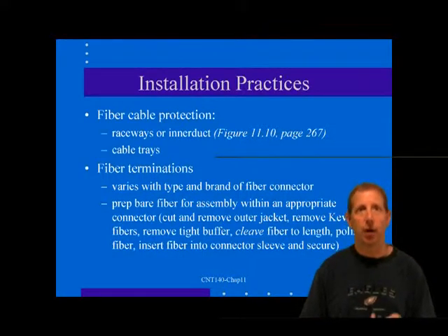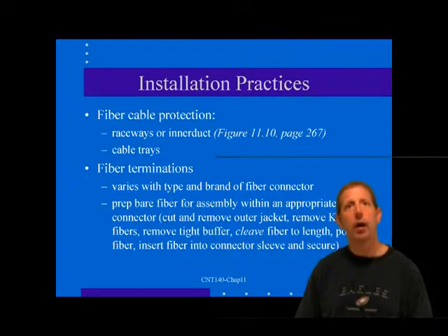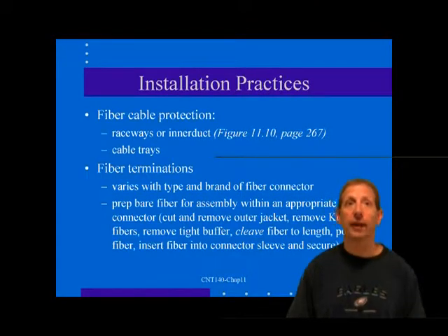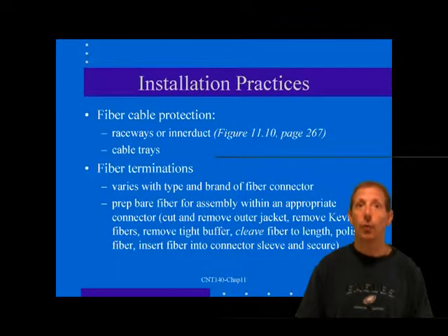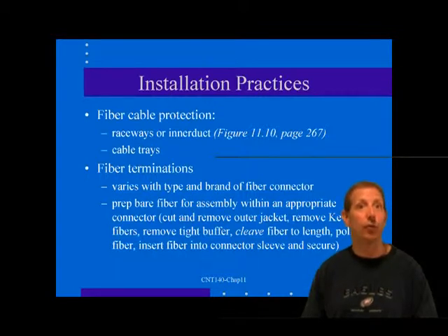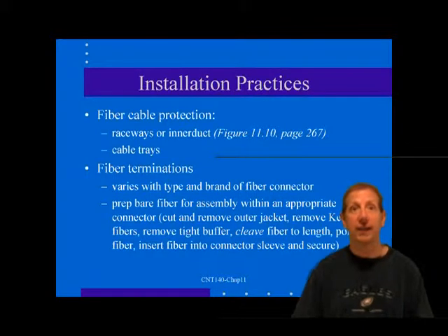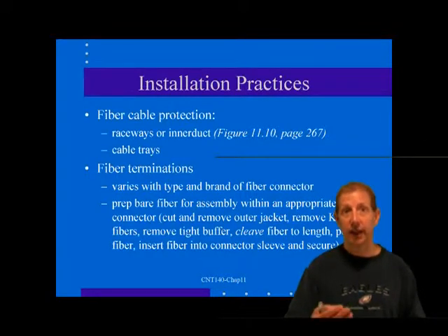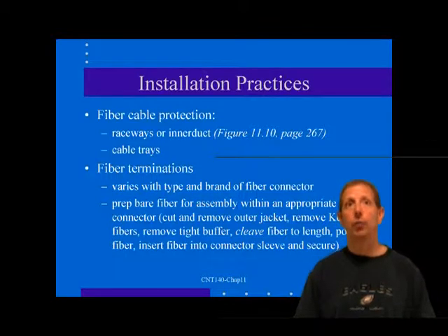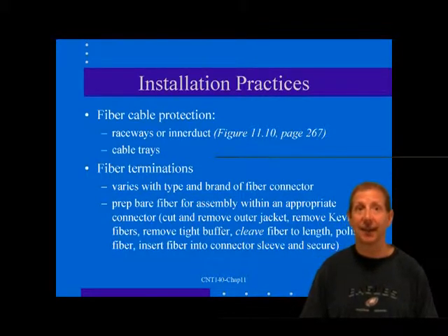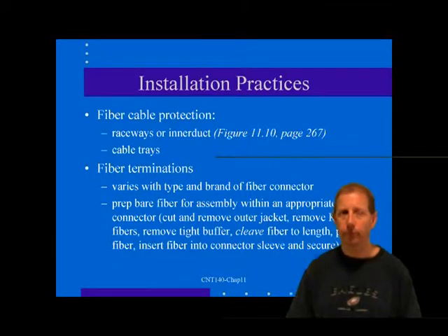One pair, although not twisted, we hope. Thus, the simplest fiber link could be 2 fiber strands with as little as the primary coating protecting the fiber. Conversely, a fiber link could be the same 2 fiber strands, but with tight buffer, strength members, thick jacketing, and even armor or embedded steel cable. The first cable type would need several types of protective routing devices, while the second type would need virtually none.